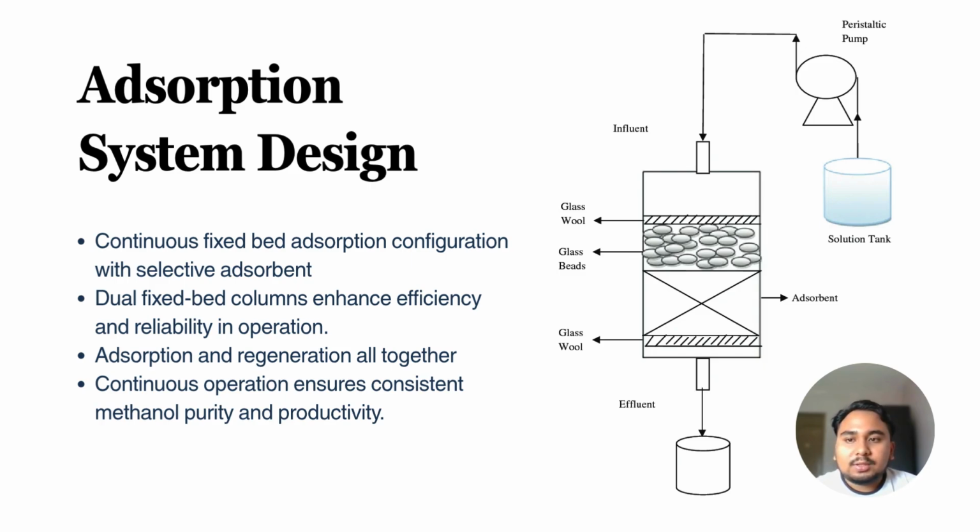This process also uses a dual column adsorption system that provides a necessary framework to maintain continuous system operation. What this means is we use one column to do the adsorption while the second column will perform regeneration.